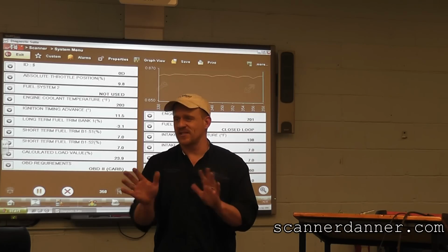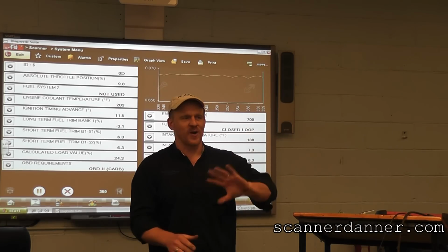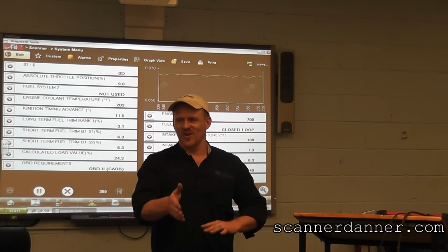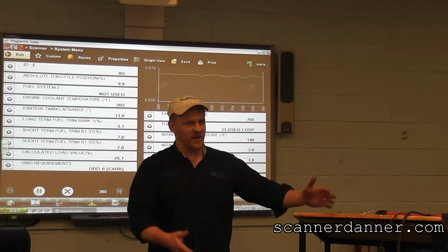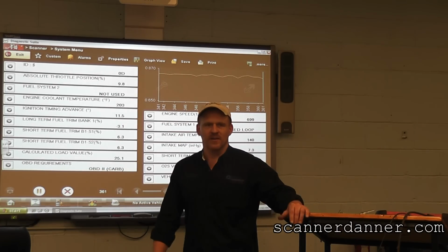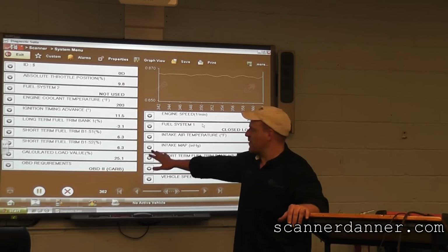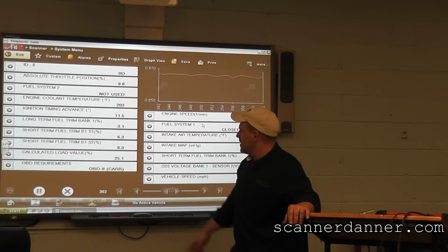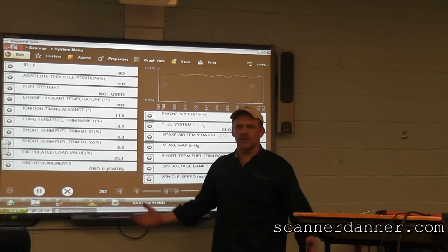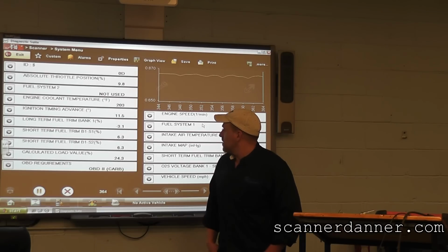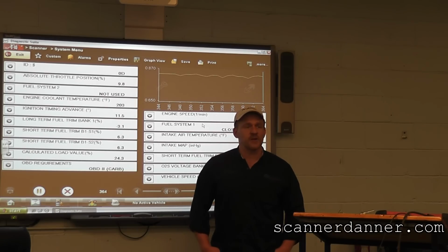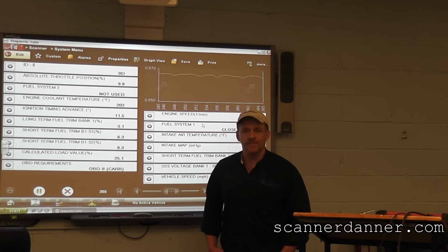And what I would do when I see a discrepancy is what? Scrub the memory and then start the car and make sure my trim numbers look good. And when they do, I'm good with that, right? But anyway, questions on that part. I think it's a good lesson here. We're still dropping on the long term. Everything looks good to me. I think when this is balanced out, it's going to be a little bit off still, but I think these numbers are going to be great.